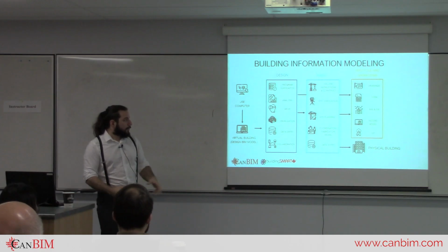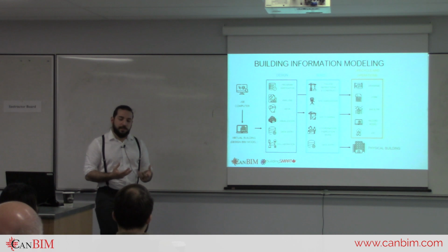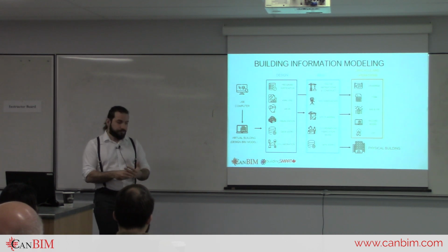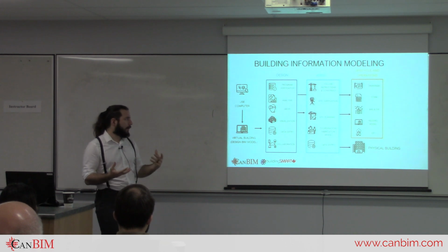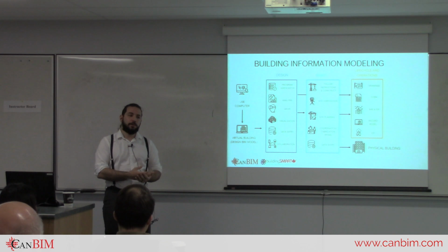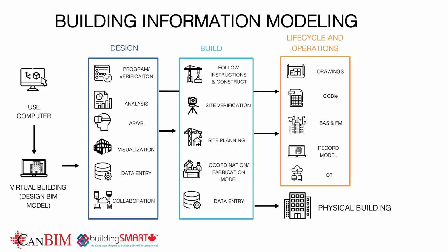And then it goes into the life cycle and operations, where now you don't only receive just a building and the drawings that are a reference for the building, but you can also get COBie output, which is a spreadsheet with all your maintainable assets that gives you some idea as to which item is where and what is their warranty period.